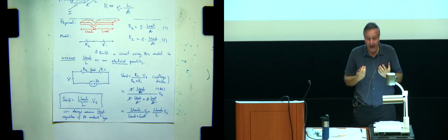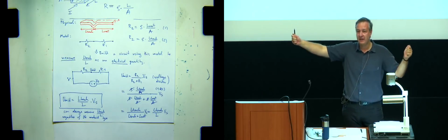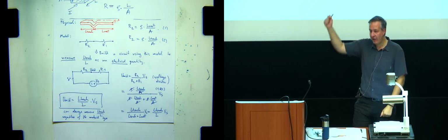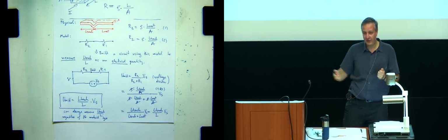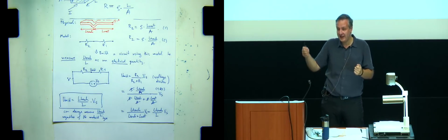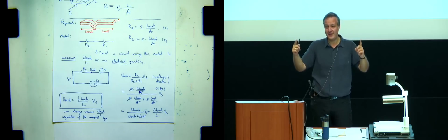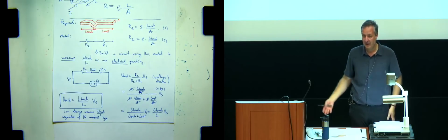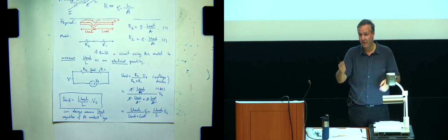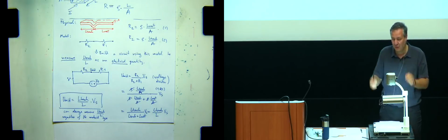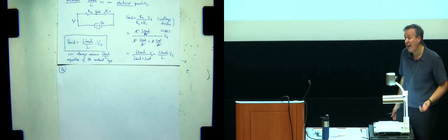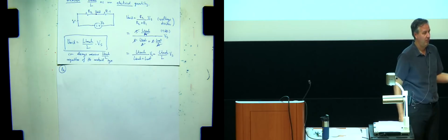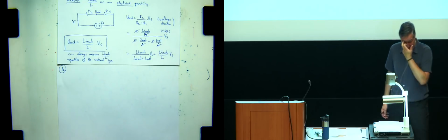That would be the case if you only had this red squishy conductor. Wherever you put your finger down, of course I have to come with a multimeter and say, hey, that's where you are. Okay, so now this resistance is R2 and the other one is R1 and I can do this whole measurement. But I have no idea where you're pressing. I would need some computer vision to see where your finger actually is, but that's another sensor. That's not what we're talking about. So, I need some way of measuring U mid regardless of where you put your finger. That's the trick.